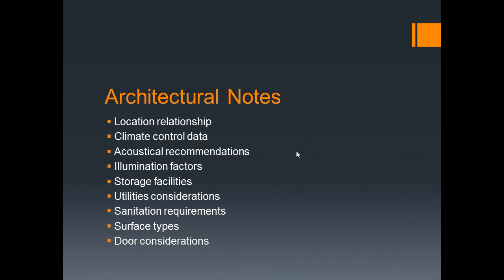And find out that the electrical bus can't carry the current that's needed. It's much, much better to overestimate than underestimate, because once it's done, it's done. So know what kind of electrical draw that lab is going to have under peak conditions. And the data is out there. Architects can get a hold of that very, very easily.